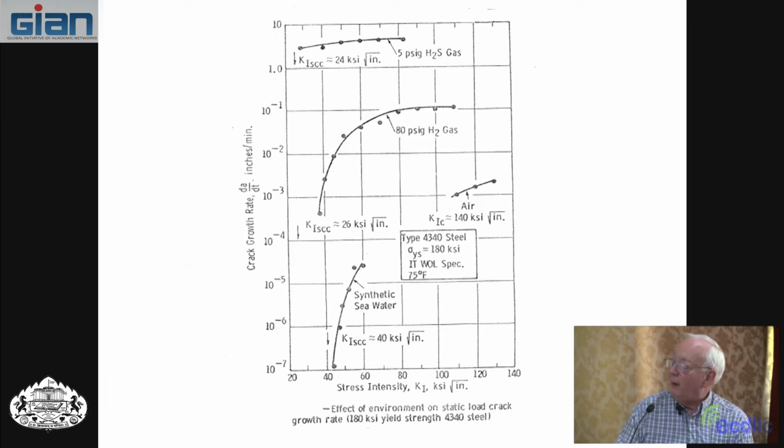One thing I wanted to point out is this is sort of a speculative thing. When you look at the effect of K, here's K versus crack growth, as you get to the lower Ks just above the threshold, the crack growth rate increases very fast. And then after a while it goes flat. It doesn't increase anymore. And chemists, not my area, said the reason it doesn't go any faster is because it has reached some chemical rate limiting thing.